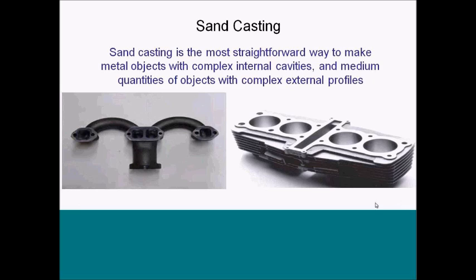Like the exhaust manifold, this engine block would be cast in one piece, and then there are going to be some very highly precise machining operations performed on the bores, these cylinder bores here, to bring them up to the correct tolerance for the pistons to work within, and then it's also got holes drilled and probably tapped to take studs which would bolt down the head of the engine. So these are a couple of typical examples of parts that are commonly manufactured using the casting process.